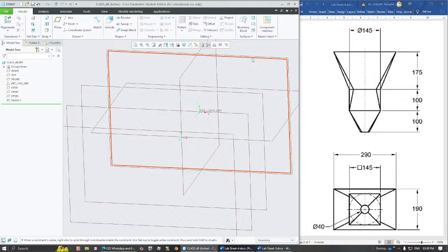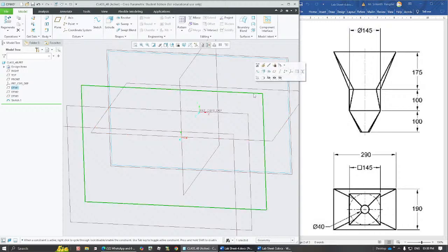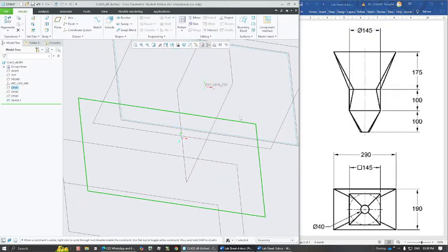So you can see the first sketch that was created was in the first plane. Now the second sketch, which is over here, which is hidden here, which is looking like a circle. So we'll have to create this on the next plane. From here, the next plane is this one. In this plane, we will have to create the next cross section, which is a circle.